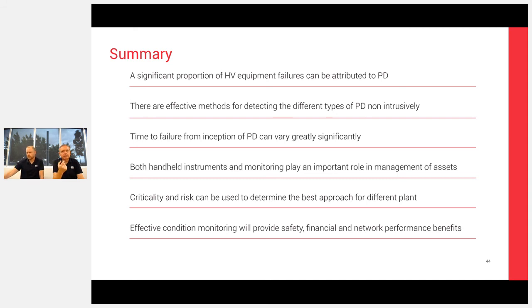And the other aspect is, are you really interested in the exact number? Is it 23 dB or 24 dB? Or are you interested in the alarm capability and the function and what it's changing and trending? So if one of the sensors were, for example, to drift, so it's reading 1 dB out, fundamentally it's not realistically going to make much of a difference in terms of the answer and the diagnostic. But typically you can go in there, say every 2 years, and check each of the individual sensors.